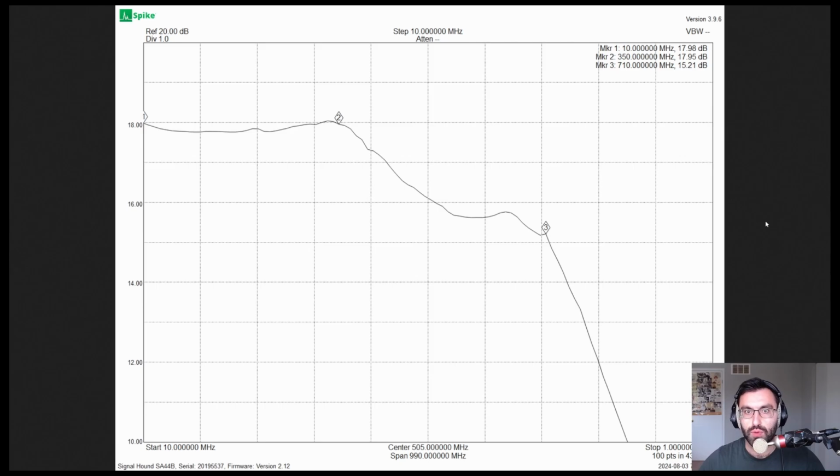Another thing to watch out for is with a PGA like this, there are actually 2 different amplifiers, right? A low gain and a high gain, and then a ladder attenuator. So the actual response is going to change over every single gain range. Here's just a selection. This is the highest gain range with the 30K R bias and the 50 ohm series, like output series resistor.